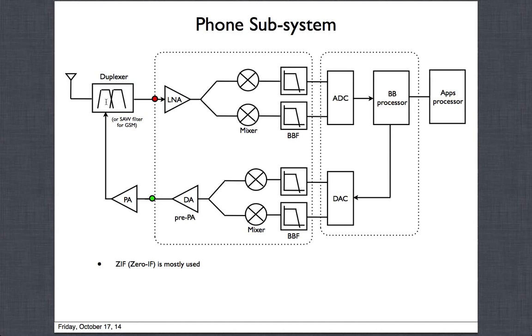Band 1 actually has the best spacing between TX and RX. But if you go to band 2, that separation becomes only like 80 megahertz. And if you go to lower bands like 850, 900 megahertz, the separation is only like 40, 45, or maybe even 30 megahertz based on the 700 megahertz bands, which are the LTE bands in the US.